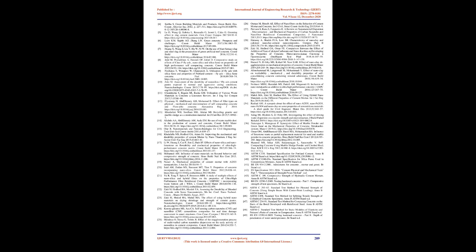For the effect of MP addition, weight loss drops obviously in the third zone for mixes containing MP, indicating the higher content of CaCO3, confirming the filling role of MP rather than participation in the hydration process of cement. TGA observations confirm the interpretations in the mechanical/physical test results and are compatible with 12, 14.